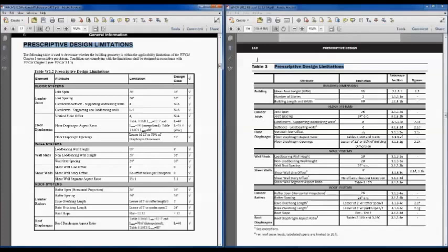The comparable table in the Wood Frame Construction Manual is Table 3, and you see here that we're mapping to that table with this workbook. Our joist spans are less than 26 feet. We're at 16 feet, so we're okay there. Our joist spacing max is 24 inches on center, and we're at 16 inches on center. And that's a common question: can I use this document with rafters or joists spaced beyond 24 inches on center? The answer is no. That would require engineering analysis.